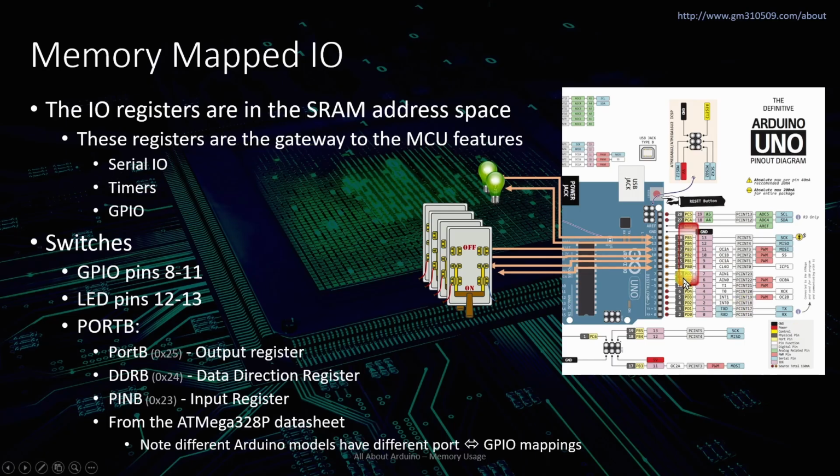That means port B, and then bit 0, bit 1, bit 2, bit 3, bit 4, bit 5. So what I should be able to do is flick the switch, and I should see the low order 4 bits change depending on the switch settings. And I should be able to write data to it and set bits 4 or 5 and affect these LEDs.